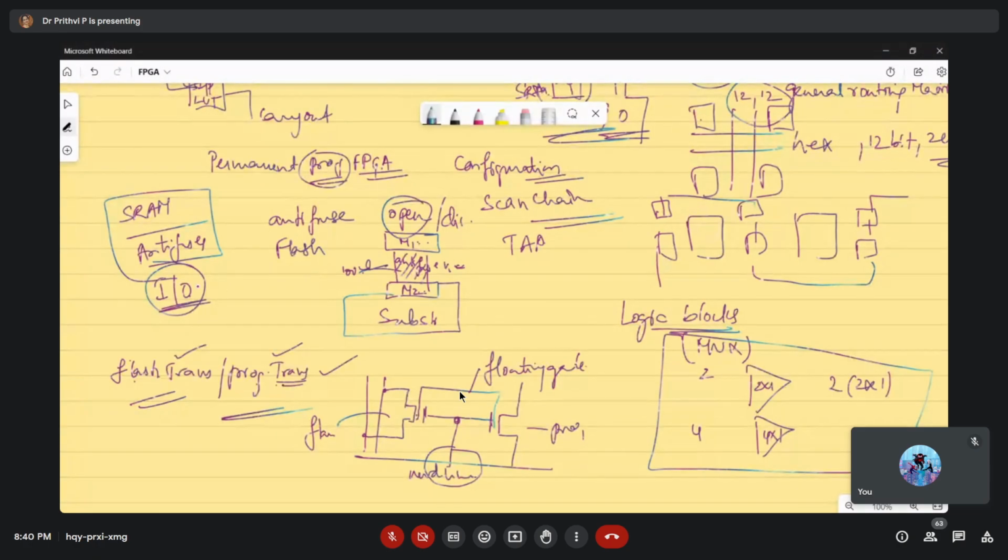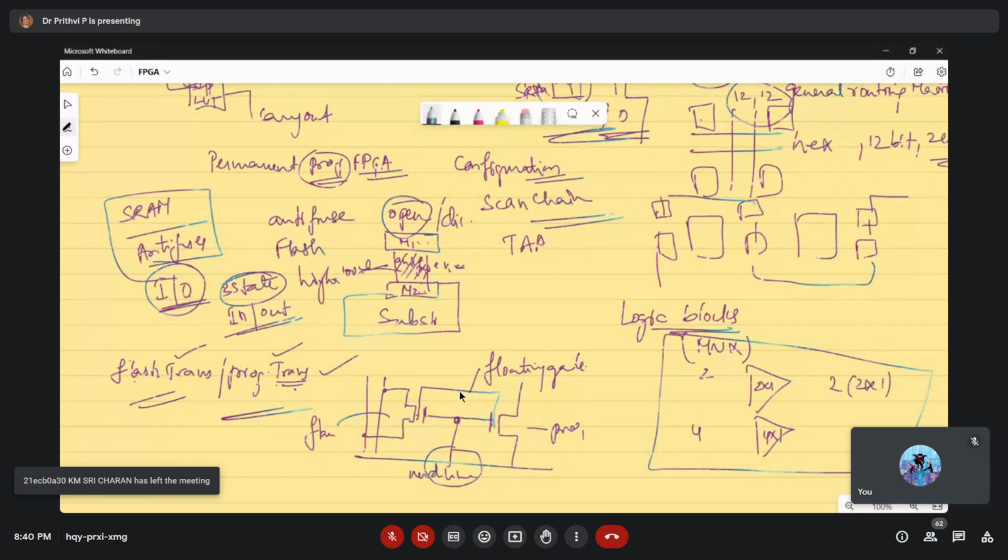Okay, and you should have the three-state aspect also, not only input and output. That means if you are not using it, it should be tri-state, meaning it should be in high impedance. If you are not using it, perfect isolation of the device when it is not in use has to be maintained. In such a condition, IO pins are perfect, as they are able to isolate the FPGA from any sort of reverse leakage values affecting it.